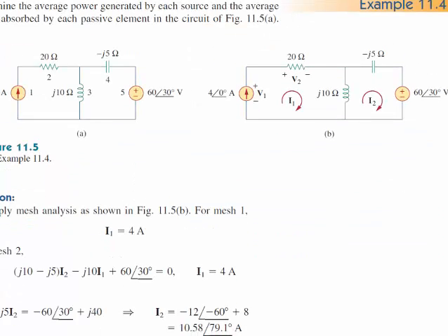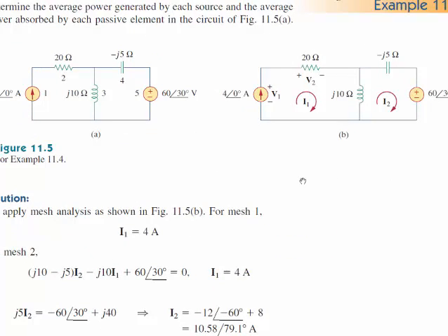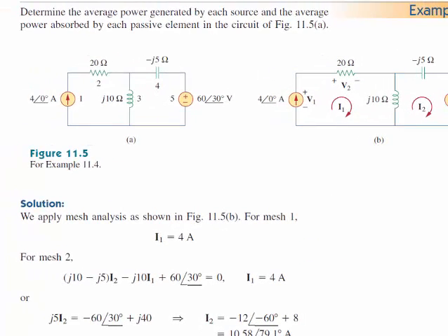So, and then the other part of your textbook is just making these problems bigger and more complicated. So now I have to apply my normal mesh analysis to this circuit and keep track of whether I have things in a complex representation or an angular representation, find currents, find voltages in the loop. But again, the thing to remember is that I can find a total impedance, and I can calculate then a total power dissipated by the circuit, but the components that are dissipating the power are the resistive components. The inductor and the capacitor do not dissipate any power.